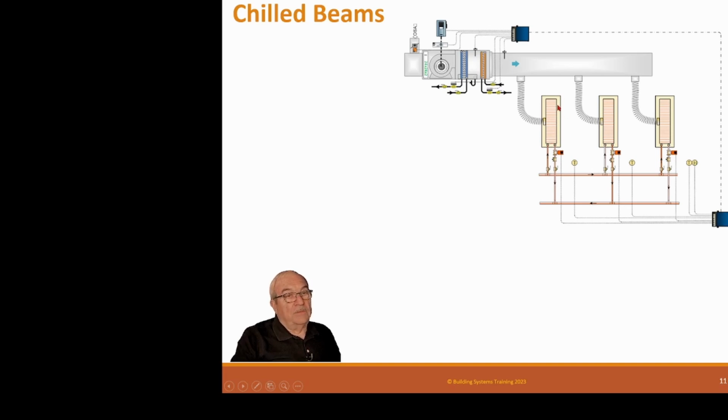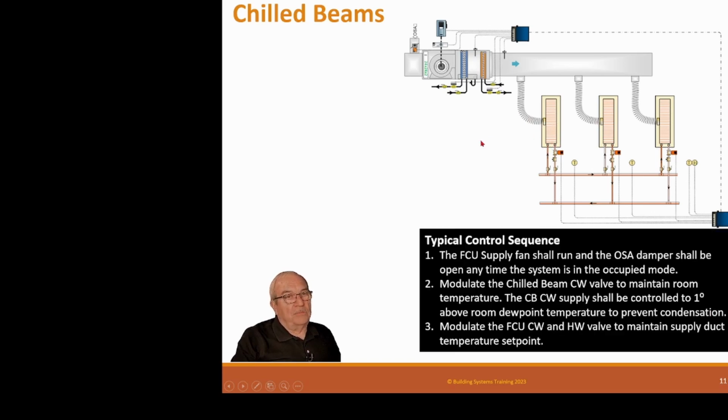And then when we started doing chilled ceilings here, we started doing some of this, and we needed more area. So we said, well, what if we put a cooling coil in there? That gave us a whole bunch more area. So we did that, and we put what we called minimum ventilation air across that, because we were using demand ventilation in the space and a displacement ventilation. And so we put it across this coil. We got a lot more surface area. And then they went to induction to induce some of the room air to that. And then these became very popular. But they really run exactly like a chill ceiling. Anyway, that's the chill beam story.